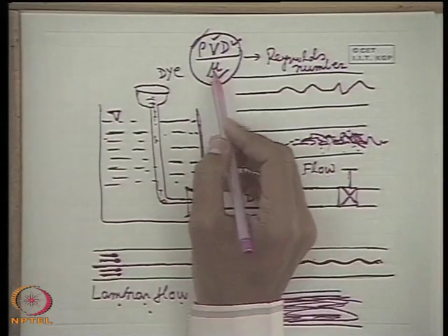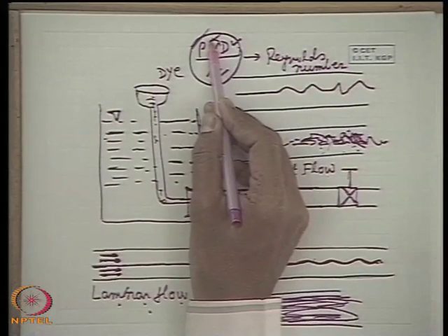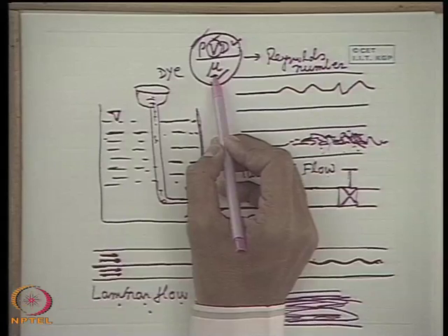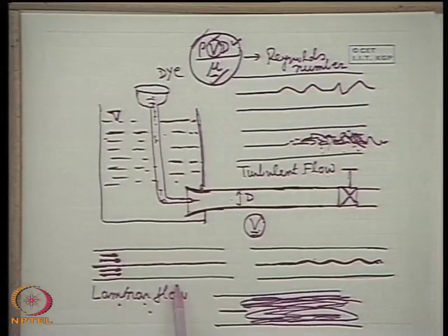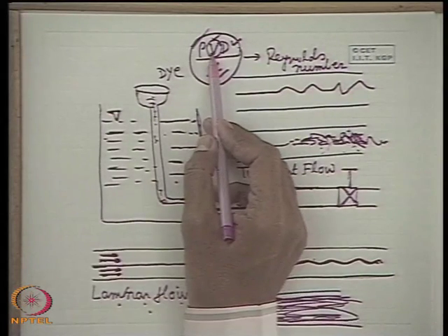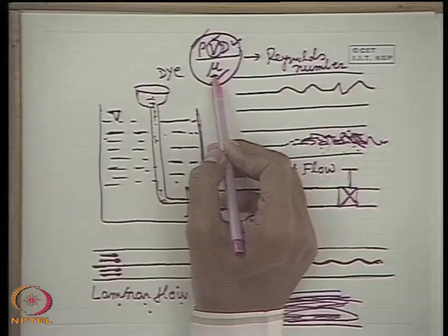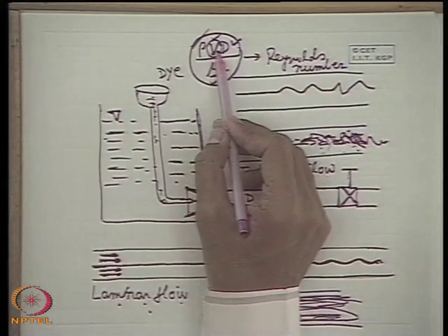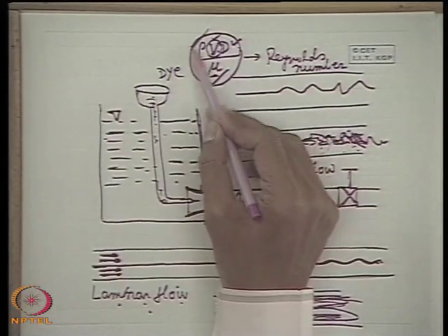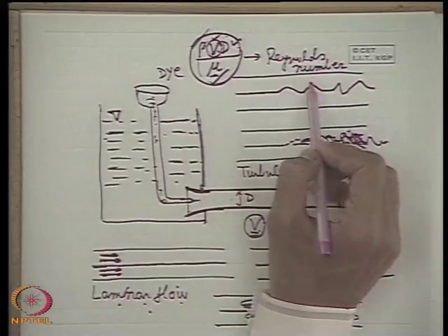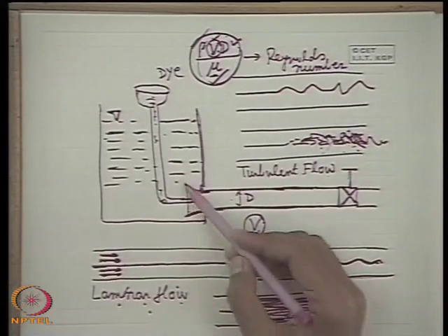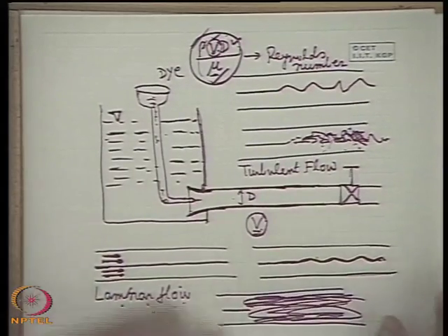Therefore the concept of velocity comes in this way: if the fluid has more viscosity, the fluid becomes laminar even at a very high velocity. But if the fluid has less viscosity, the fluid becomes turbulent even at a lower velocity. So as a whole, the combination of these parameters known as the Reynolds number is the criteria for the fluid flow to change from laminar to turbulent flow.